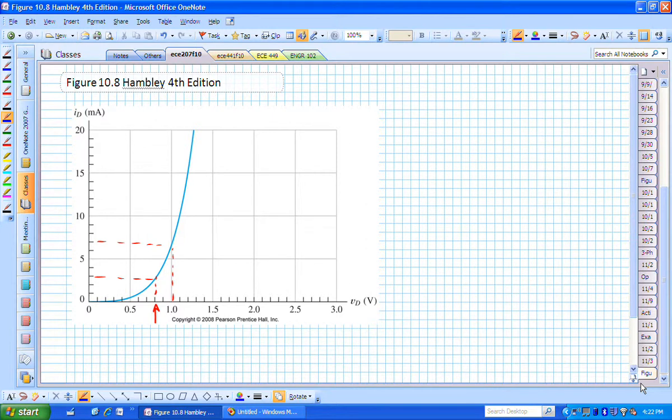So we're going to now try to find an equation or another line that will hopefully intersect with this line, and the intersecting point is going to give us the sweet spot, or where the current and voltage of that diode will be operating when this combination of KVL and this current voltage relationship are both true at the same time. Is that clear?